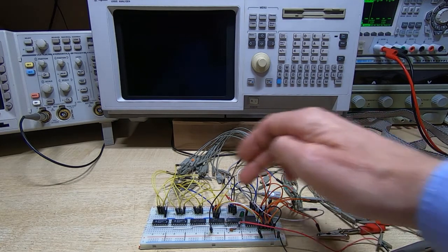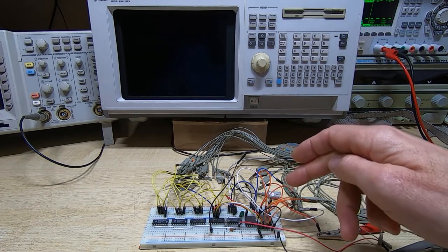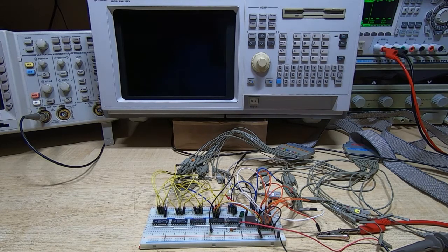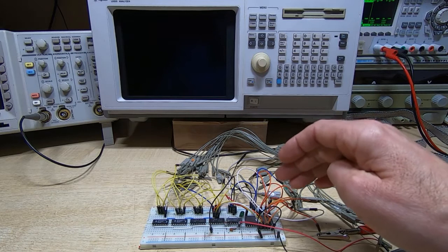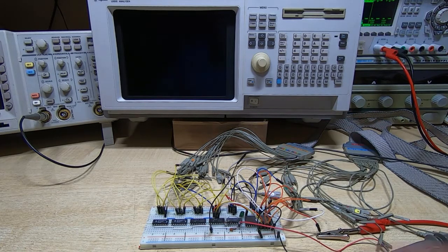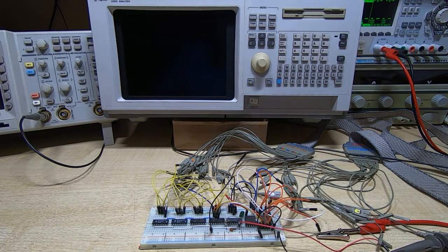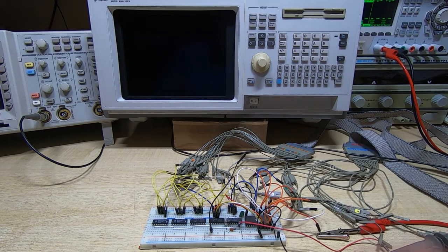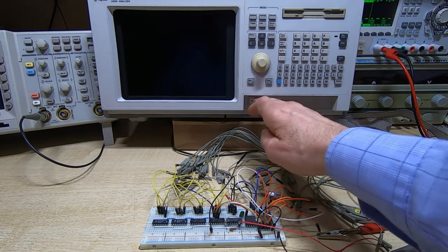Now in this case, the way I've got this configured, I've got the ROM set up so that it is enabled whenever bit 15 of the counter is high. So in other words, it's effectively mapped to address 8000 hex. So the bytes we're interested in are mapped to 8000 up to 8007 hex. So that's what we want to try and filter out from the rest of the data. So I'll start by powering up the analyzer.